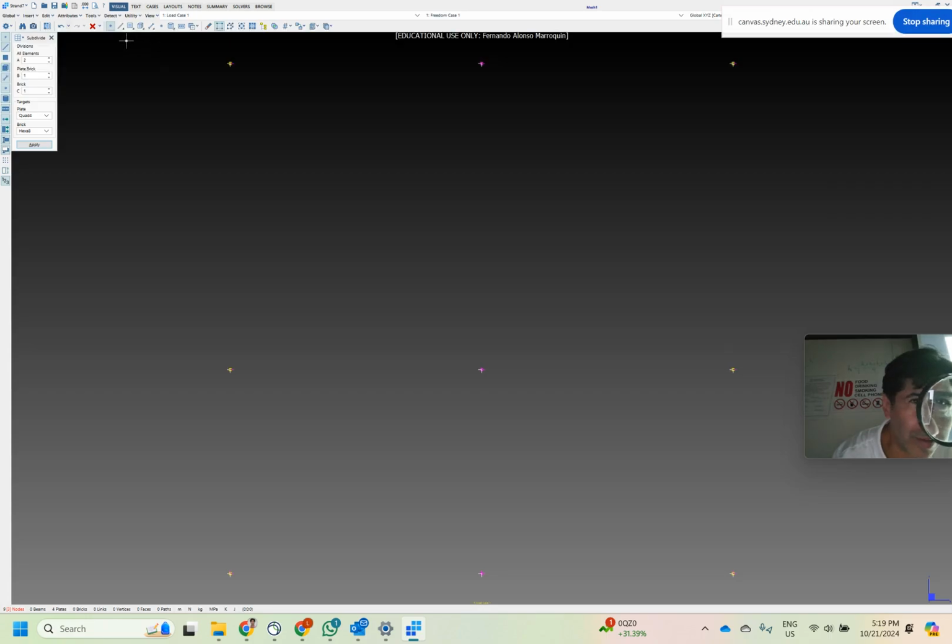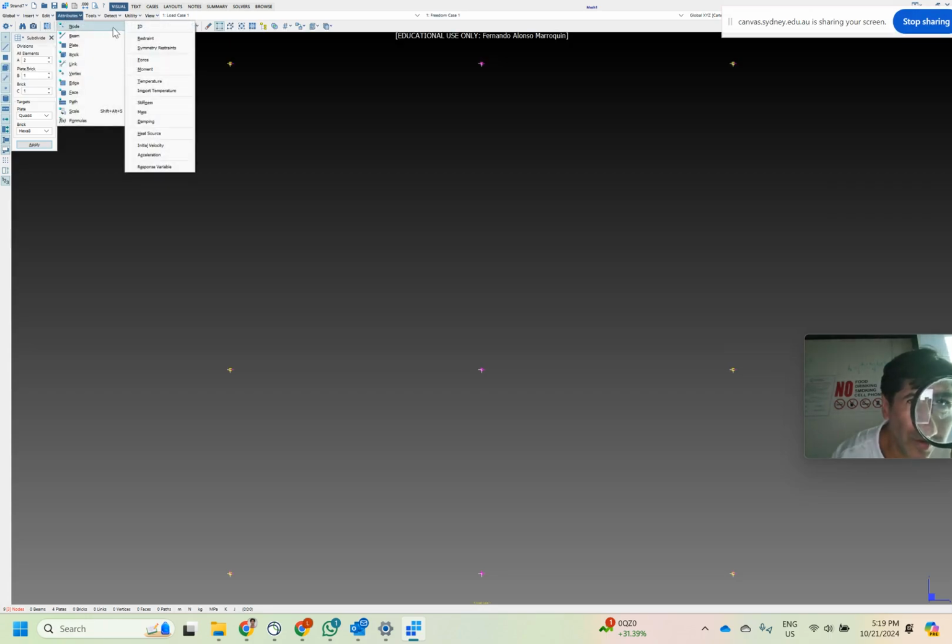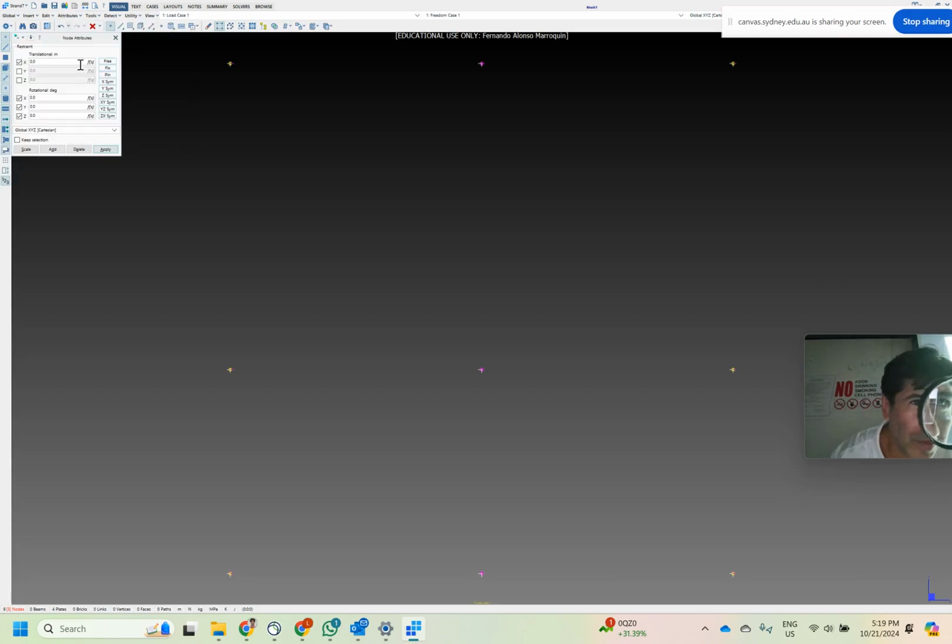So three selected, and then attributes, node, restraint, and I'm going to free them. Free these three, apply. Okay, now they are free. Ah, but this one, no, one moment. The bottom one. Okay, better.